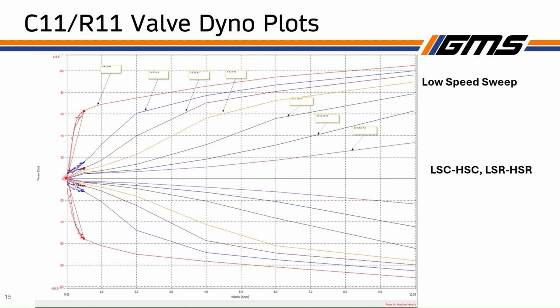Now, you can see that the slope for the different amount of low speed clicks in the low speed region, that changes, right? But the high speed slope doesn't really change all that much, right? And there's a certain threshold where the high speed region starts, and that doesn't really change either. You can also see that there's the compression stroke, and there's also rebound down here. Technically, all of these graphs should be like in quadrant 3 of the graph over here, but Öhlins just gives this to you in absolute velocity.